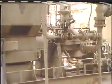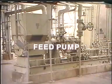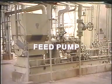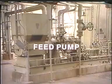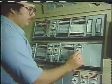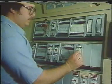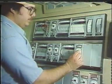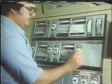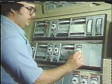The feed or charge rate to the reactors is a third operating variable. Normally, a constant amount of feed is charged to the reactors at all times, but feed availability problems or mechanical difficulties may occasionally force a feed rate reduction. If the feed rate decreases, the system will be thrown out of balance unless other operating variables are adjusted. When less feed is being processed, the reformate octane number can be reached at a lower temperature, so the reactor temperatures should be reduced until the feed rate returns to normal.